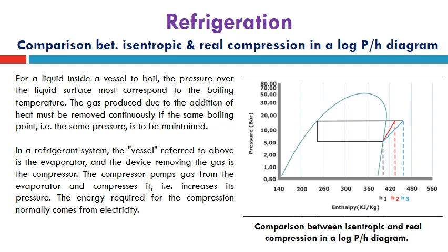We can find here the starting point of compression, which is located on the saturated vapor line, and in case of isentropic efficiency equal 100%, for isentropic compression we will use this red line to get H2, which must be located also on the condenser pressure, the second location for this line, and the first location is constant S line. Based on S2 must equal S1 using this constant S line shown in red.